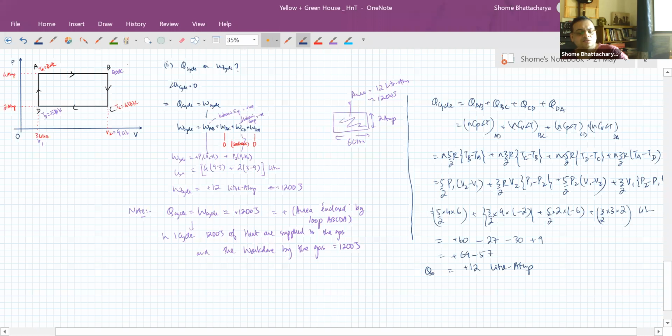But you can see how much more inefficient this process is, because I'm having to apply the formula, and then substitute CP, CV and all this for each of the processes. Whereas in this case, the calculation for work done was much easier. And we know by the definition of a cyclic process that delta U has to be 0 because we are coming back to the initial state. So obviously the state function has 0 change.